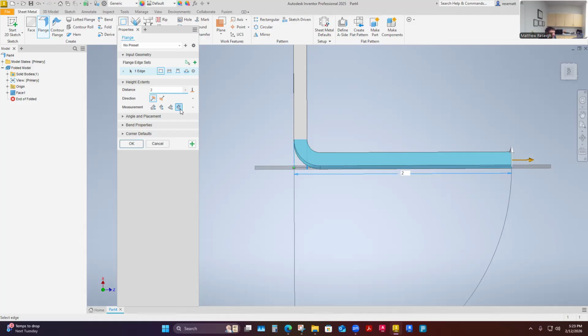But the reason is because everybody's bending equipment is slightly different, even probably if it's the same machine delivered to two different manufacturers, the way they set it up, whatever. There are some effects on this where I need micro adjustments in order to match what my machine produces, like what I anticipate from a design. And this is how manufacturers have to do this. If they get a new machine and they're running this program, they may have to kick out a few part strips to go bend and decide how it's responding to these materials.